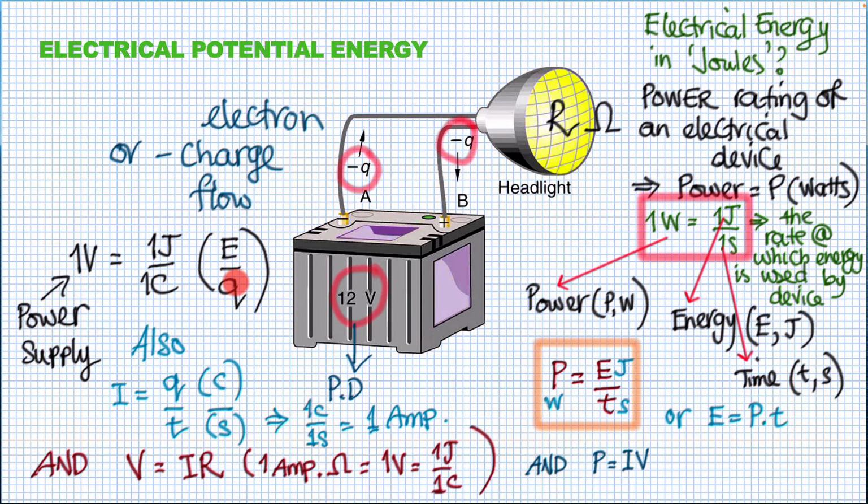So in conclusion, we can determine the power rating, or the amount of power that's dissipated, or released, by a resistor in an electrical circuit, using this equation P equals IV, and we can actually combine Ohm's law in this because we can substitute here for V, or we can substitute for I based on the appropriate resistance.